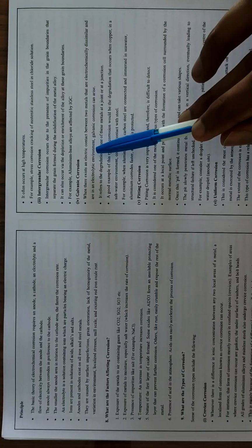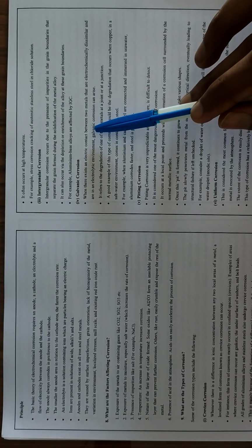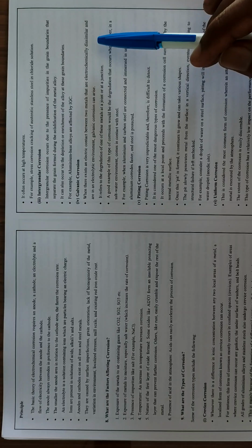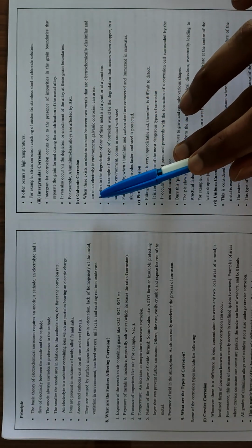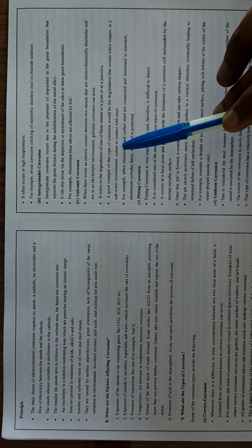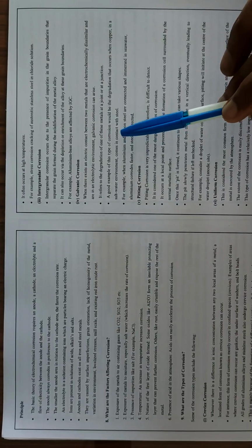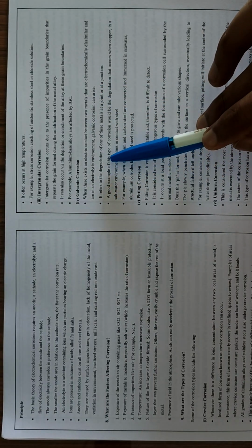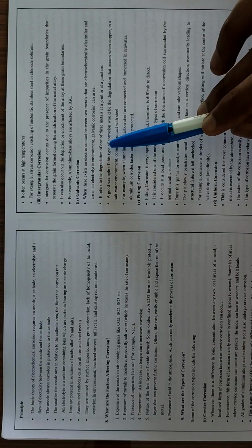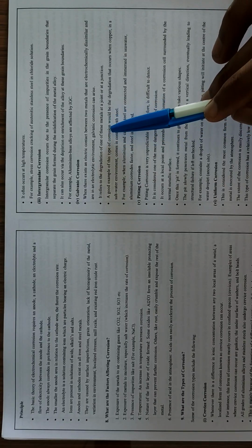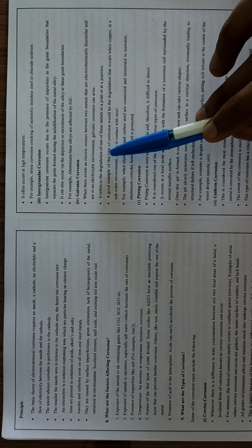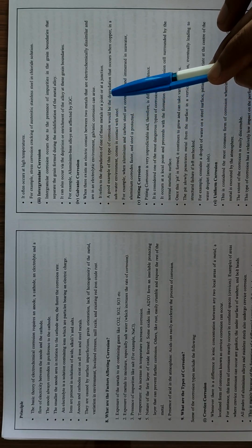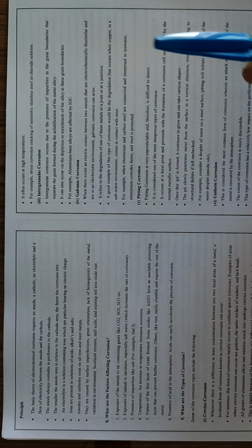Galvanic corrosion can arise when there exists an electric contact between two metals that are electrochemically dissimilar and are in an electrolytic environment. It refers to the degradation of one of these metals at a joint or at a junction.